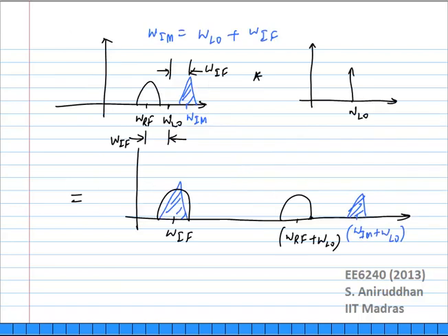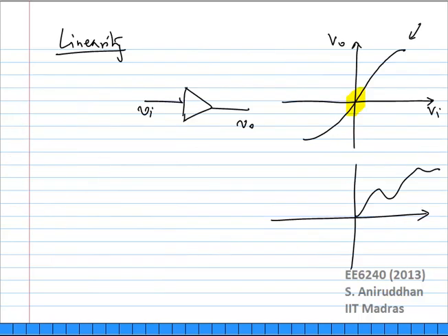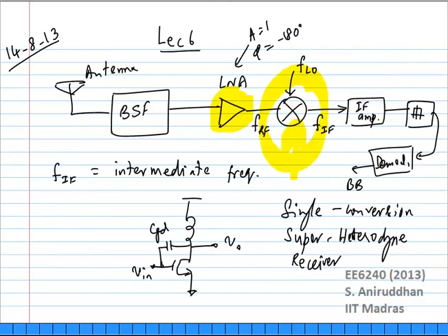So what that means is you actually need, let me just add that block here. I'm going to call it the image reject filter. I need it just before the mixer. Okay. So now this image reject filter obviously is rejecting something, it's operating at what frequency? At the RF frequency. At or around the RF frequency. It's trying to cancel out the image frequency.